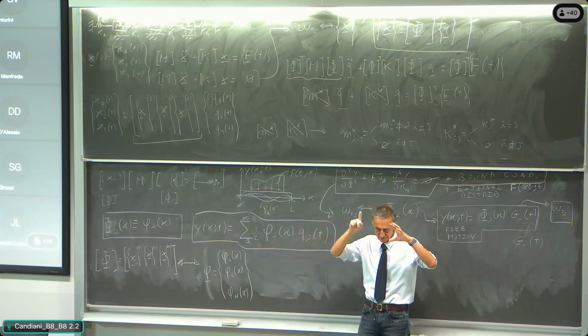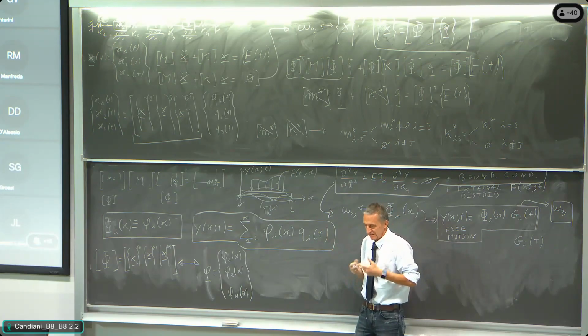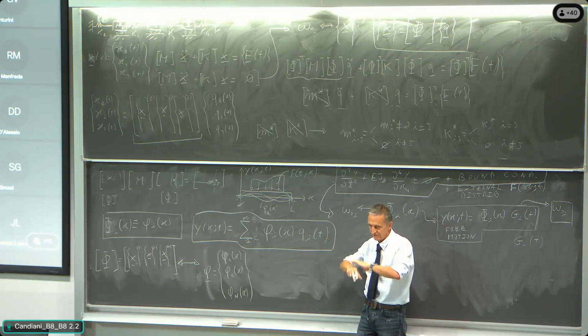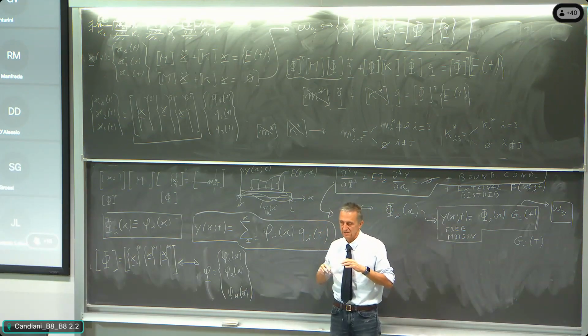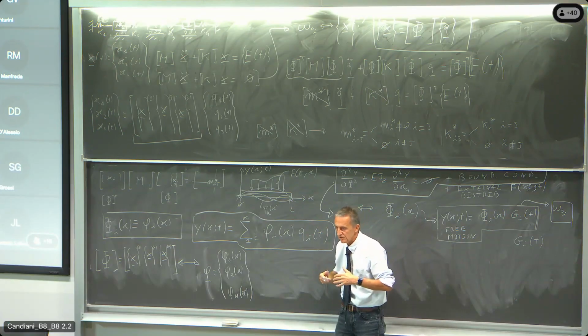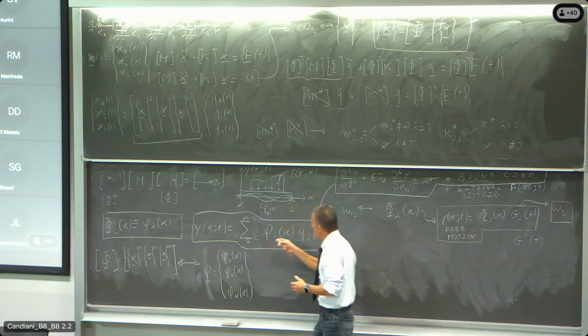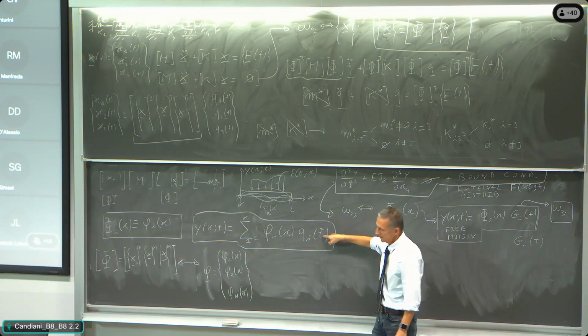You take a snapshot, you fix the time, and you take the picture that the structure has. And you pretend that this shape, whatever is the possibility in the infinite space of configurations of the structure, can be represented by a combination of the modal shapes, each of them multiplied by a real number.